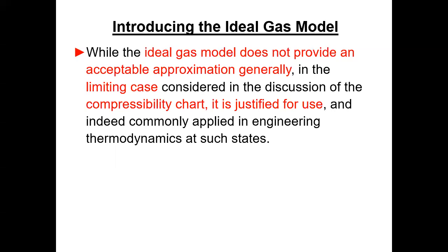And this is true, and that compressibility factor chart is the illustration of that. When you calculate that Z and it comes out to be 0.35, you're going, well, crap, that equation doesn't work very well if I have to throw a factor of 0.35 in it in order to get any sort of halfway reasonable result. So the first and simplest approach is to go ahead and just look up the compressibility factor, or curve fit that, or somehow put that into your analysis. But then you'll see that there are much more complicated and better equations of state that you can use and plug in.